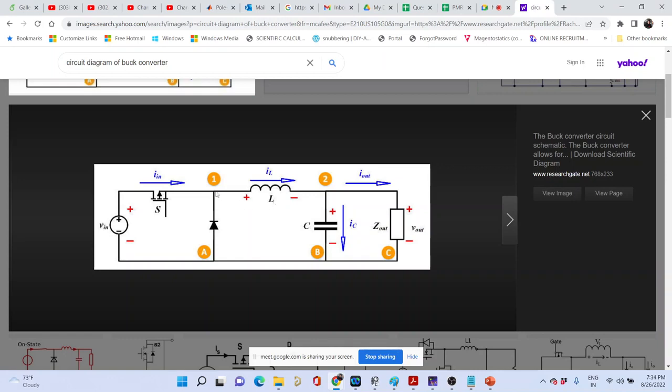No. Why additional voltage? You see, you have an inductor over here, you have a diode over here. At this point you have a voltage stiff element. The voltage across the capacitor will not change significantly, so you can say that this is at a fixed potential. There is a current stiff element over here, and there is a diode. And you don't know whether the diode is conducting or not, but you have to apply this positive voltage or negative voltage to turn on or turn off the switch. How do you do it then?